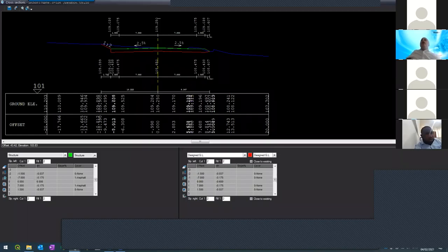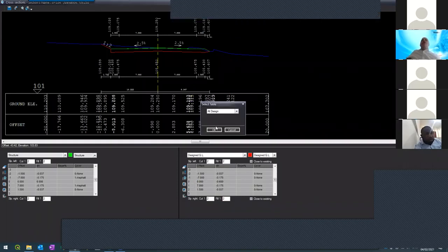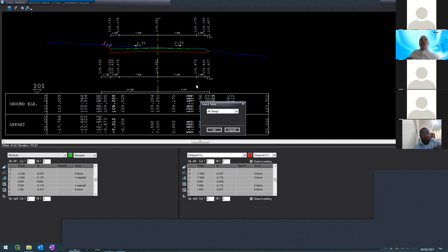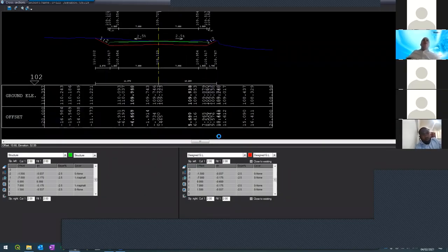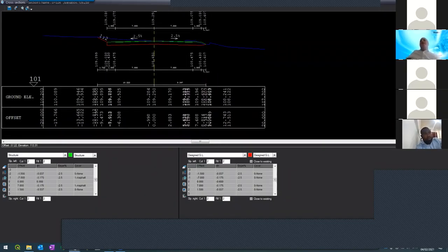How do I do it? I'm pressing this button, interpolate empty sections. What the system will do, it will now scan all the sections. Each section, it will refresh it, and if it's empty, it will interpolate it. That's it. Usually it's very fast. And now I have all the sections.